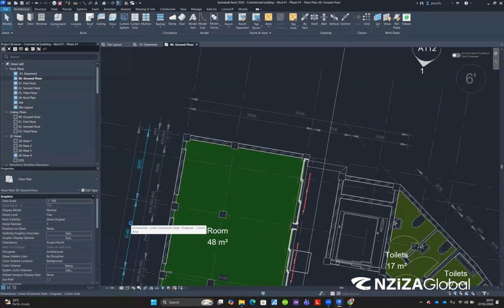Use the metric one. But you need to check the Revit file you downloaded. Maybe it is the student version, because it is not bringing the templates. You are supposed to find the structural template, architectural, plumbing, electrical, things like that. So you need to check very well.